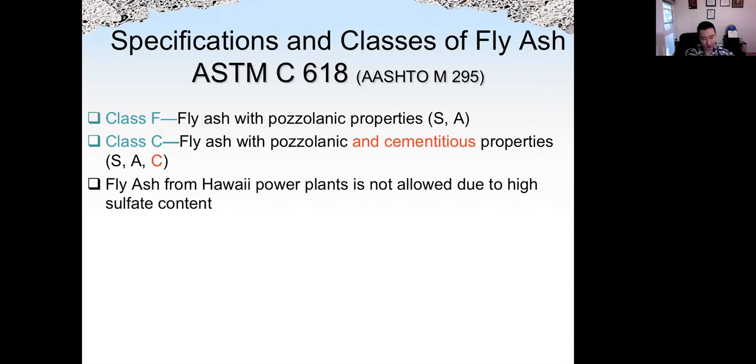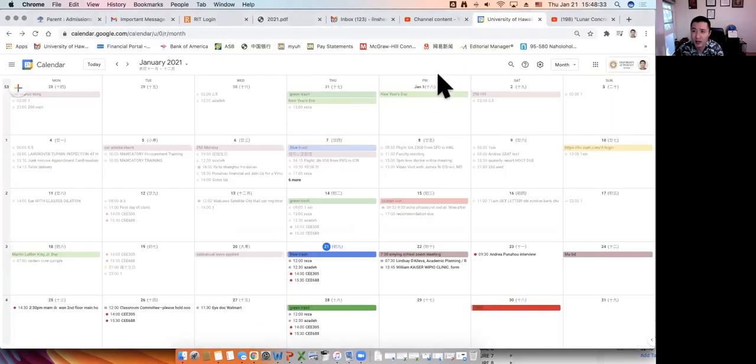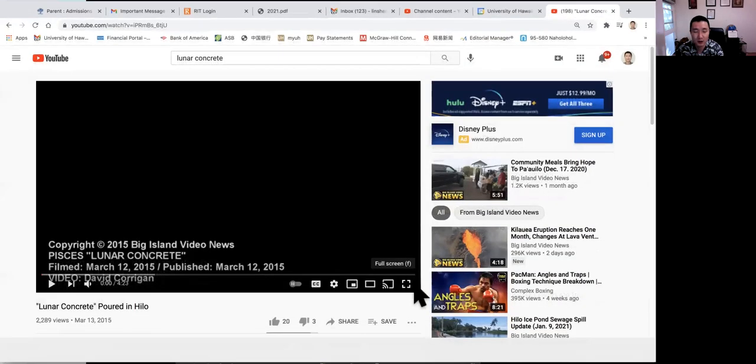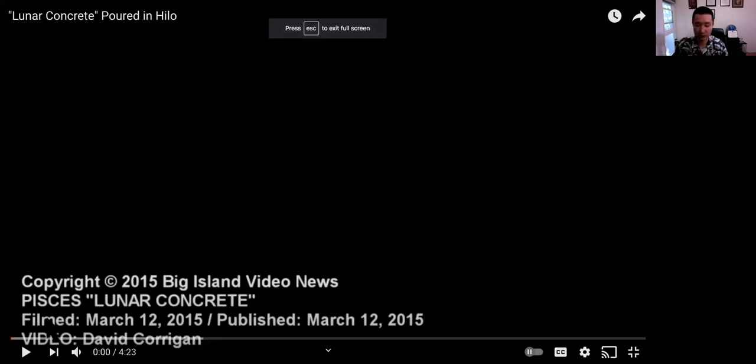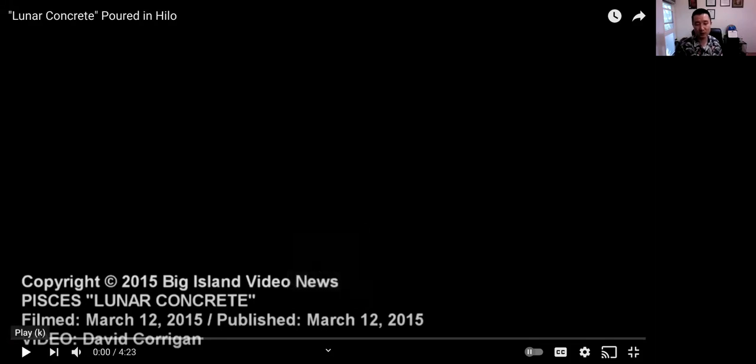I'm going to show you a video which is about our research project. We have been working on this project for more than 8 or 9 years. This is one video about so-called lunar concrete. And this is actually a concrete with no Portland cement at all. We use fly ash together with some other mineral admixtures such as slag to replace 100% of Portland cement.